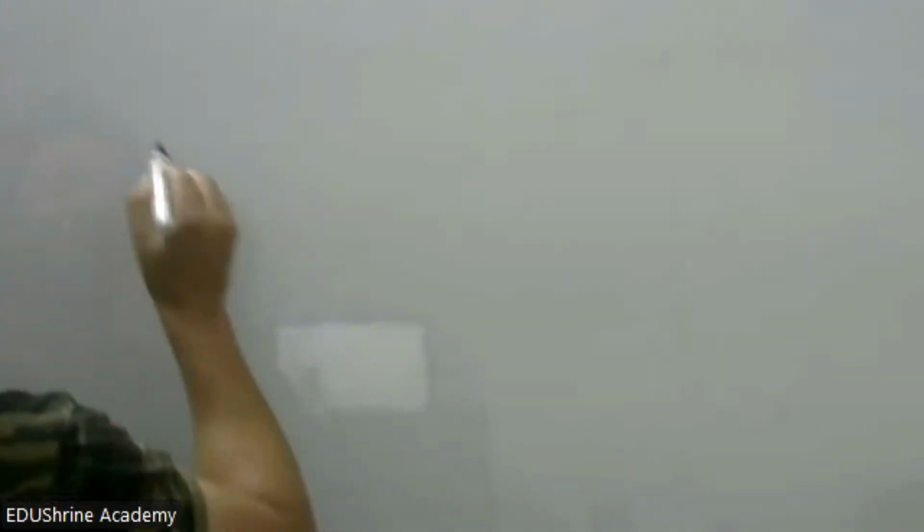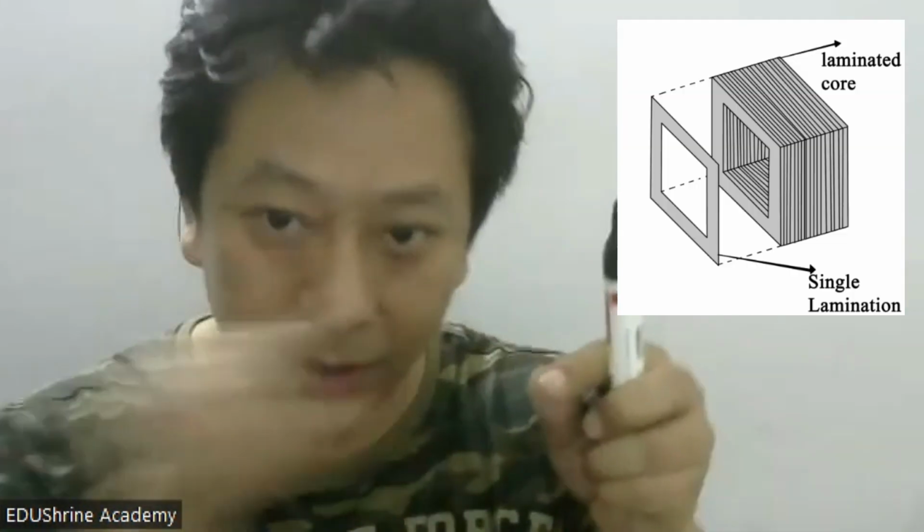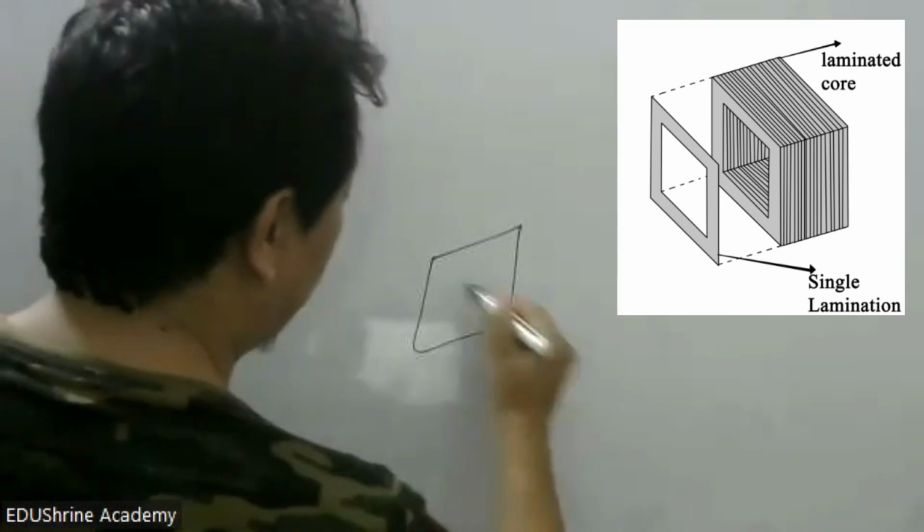Okay, mention this. We'll see the working now. So how does it increase or decrease the voltage? It's quite simple actually. The way the diagram looks, it takes a bulk soft iron as a core. What is the core? The inside. So it takes a solid soft iron body, and then it laminates. Laminating basically means cutting the bulk conductor into thin sheets. Okay, and then making a rectangular hole kind of thing. So if I show you a 3D diagram, it will be something like this.